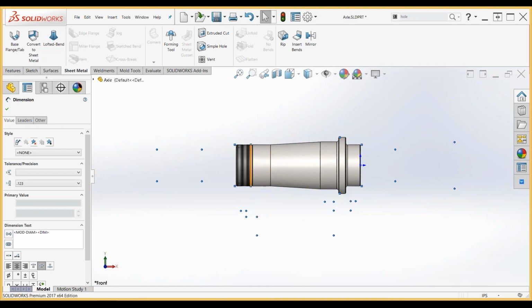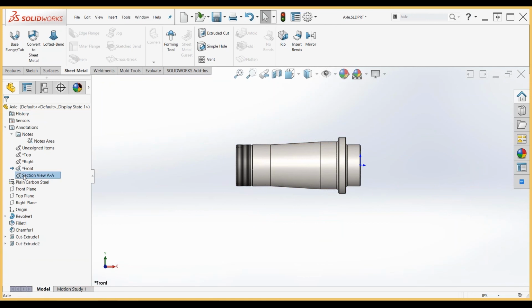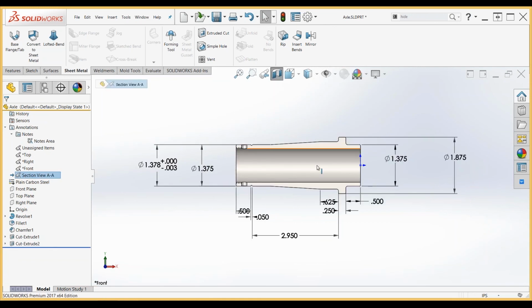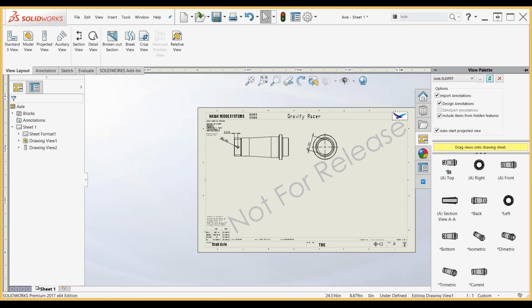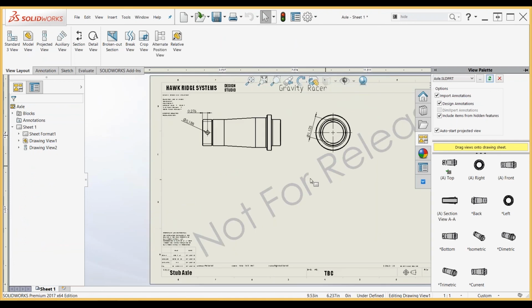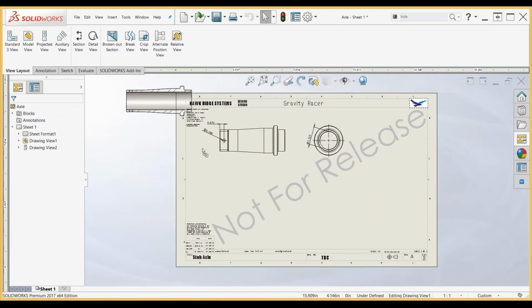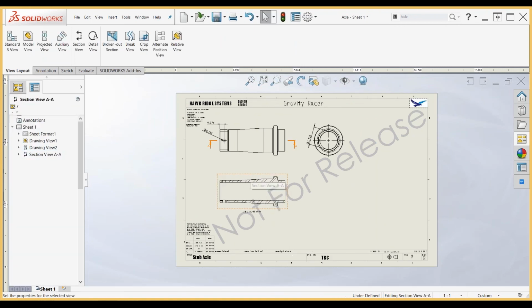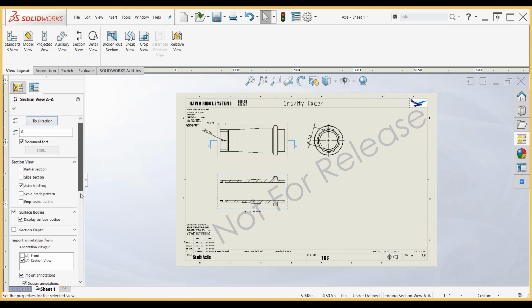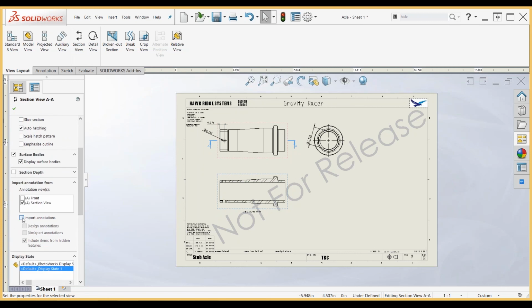So when I create it, I come in here and I choose, okay, maybe I want it to have this title block. So it will have that sheet format. And then using that selection tool, I can apply different sheet formats to multiple sheets. So if I have 10 sheets, I can say, okay, apply this sheet format to sheets 1, 8, 7, and 6, even though I said I only have 5, but they're numbered that way in my imagination there. So the answer to that question is yes, you can have different title blocks for different sheets.